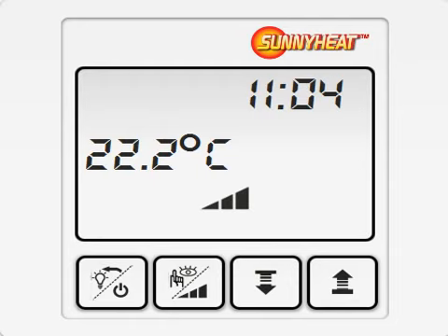After pushing the fourth key, you should be back in the main view of your ISTC. That was the whole connection process. Your SUNNYHEAT ISTC and heat panel are now able to communicate with each other and the warning triangle should be gone. Learn more about your ISTC in our additional SUNNYHEAT video tutorials.